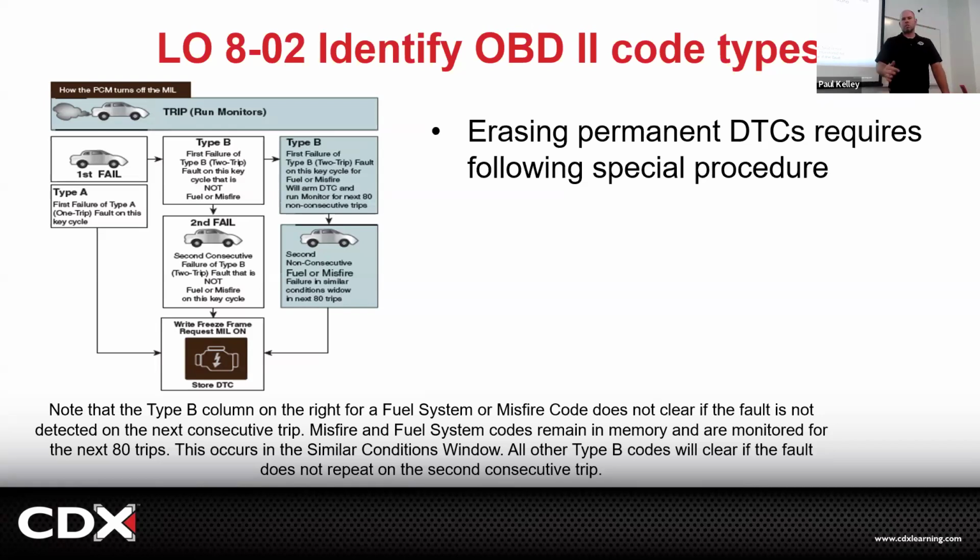So the customer just kind of got ripped off, but also, wouldn't you say, the car put out more emissions because it didn't get fixed right the first time? So the government rolls out, the EPA, and they're like, hey, permanent DTCs. If it sets this DTC, you can't clear it. I can't clear it. No scan tool can clear it. Disconnecting the battery won't clear it, right?